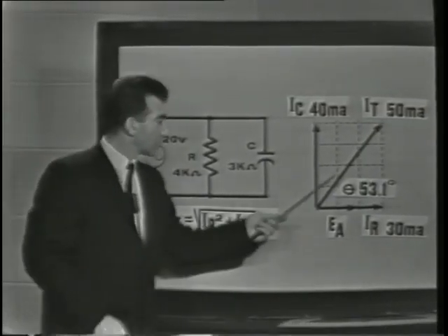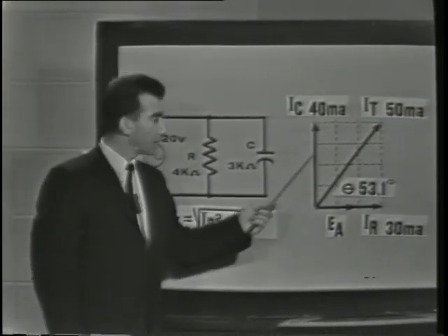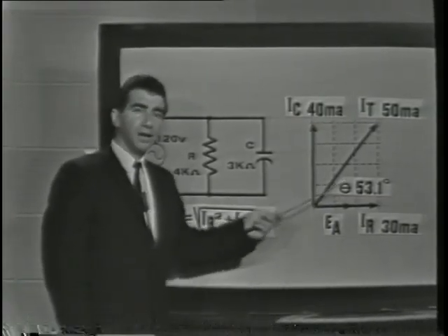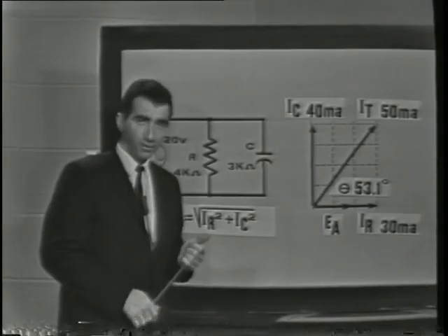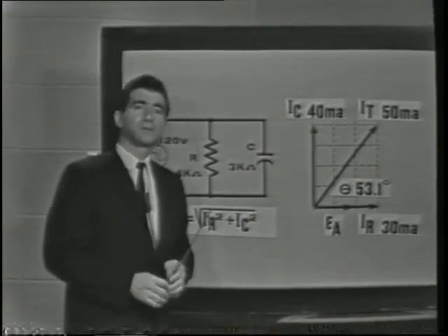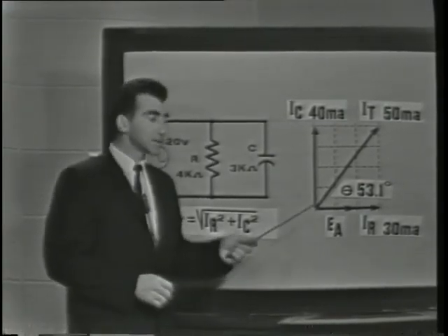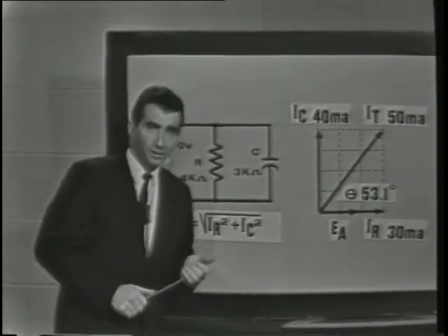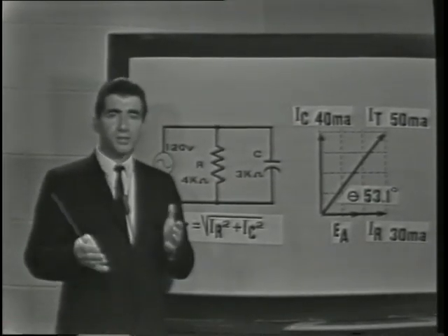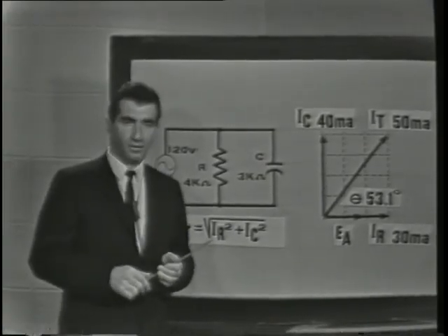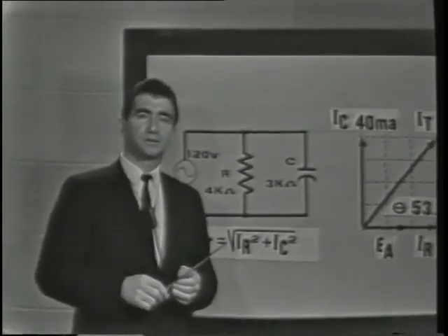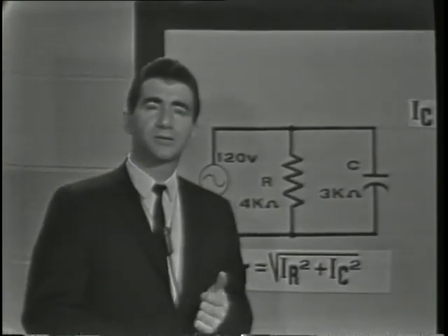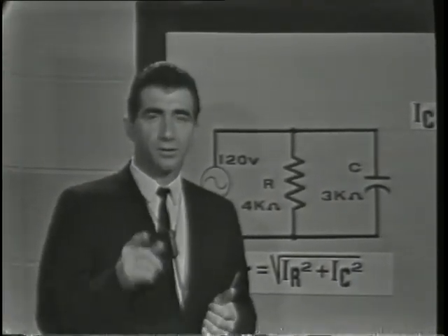And the phase angle can be determined, once again, by simply measuring the graph, or more exactly, by calculating the sine or cosine of angle theta, or the tangent, and using the trig tables. The phase angle is important to us because it gives us an indication of the power factor, which we defined as the ratio of true power to apparent power. Now, the facts we've discussed concerning this circuit will become more important to you as you gain additional knowledge of their application. So know them well.